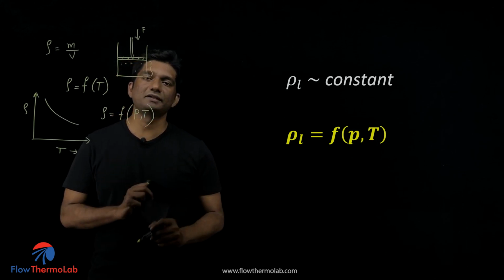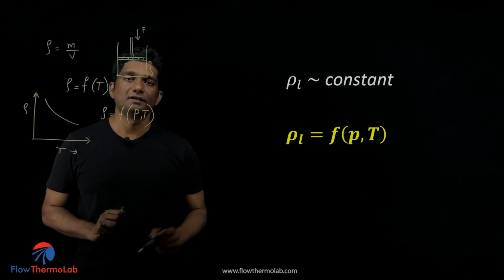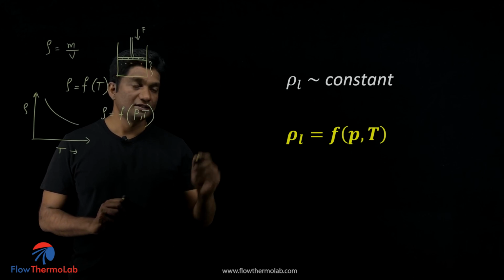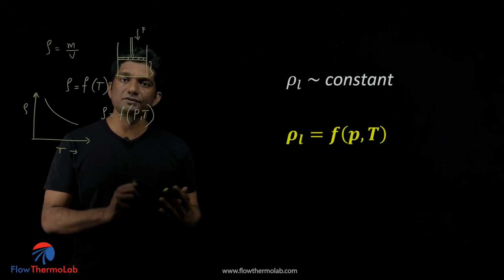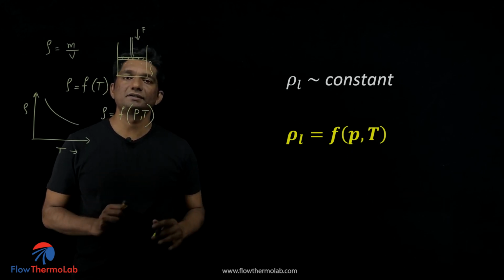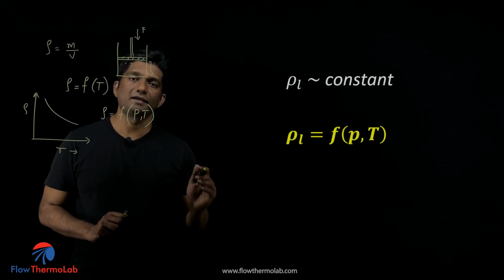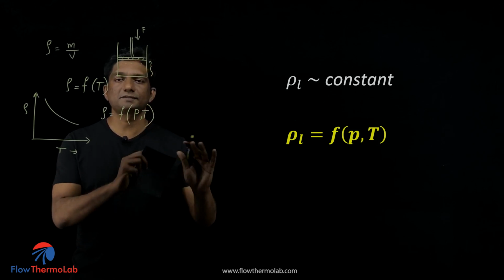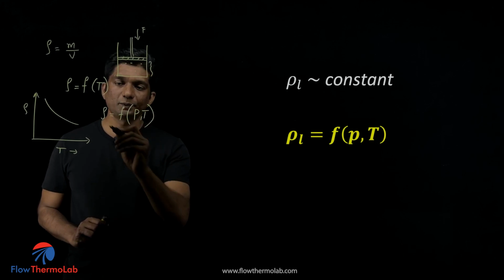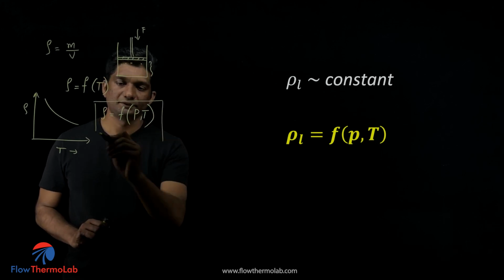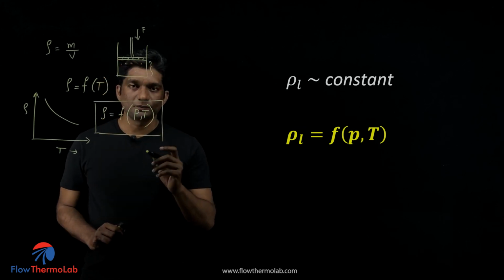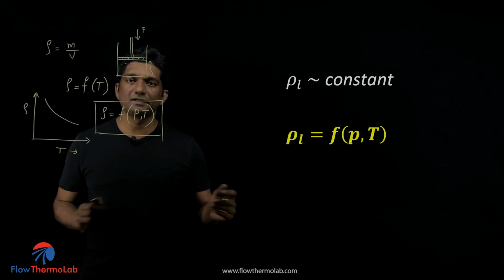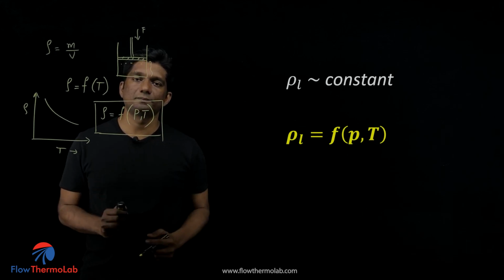At 2000 bar or 2500 bar in diesel engines, the fuel is compressible. So you have to treat diesel as compressible in these kinds of conditions, and then do all the calculations. Similarly, in GDI engines, you are using gasoline. Even if the pressure is like 100, 200 bar, it can also be compressible and the density can vary. So these are special applications where liquid can be compressible. And also in liquids, in special cases, even if it is water, it's not going to compress much.